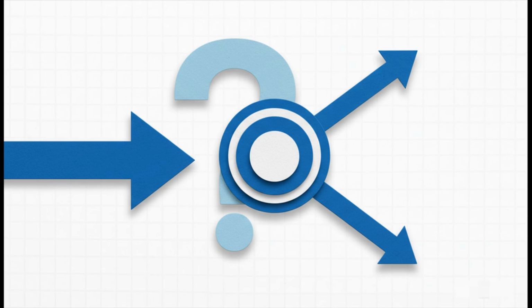And this right here, this is the whole key to the puzzle. You've got the main current flowing out from the battery, right? And then it gets to that node, that junction point, and it has to split. It's like a fork in the road. One part goes one way, the other goes another. The moment you see current splitting like this, a little bell should go off in your head that says, aha, I'm definitely going to need Kirchhoff's current law here.